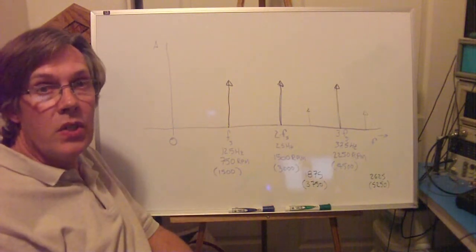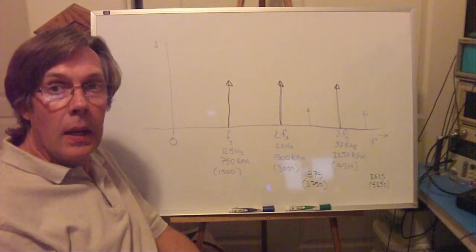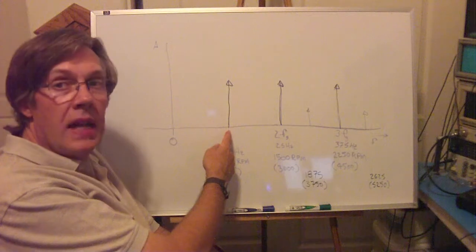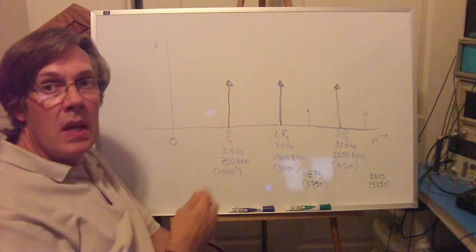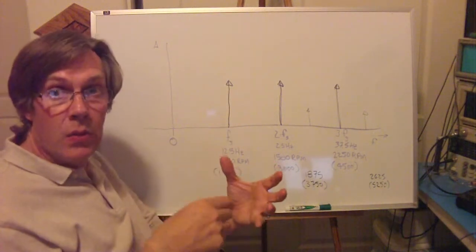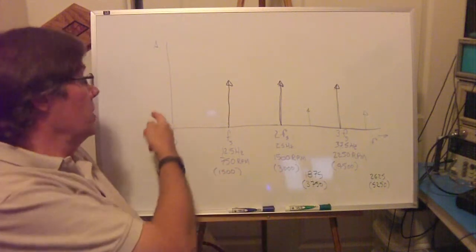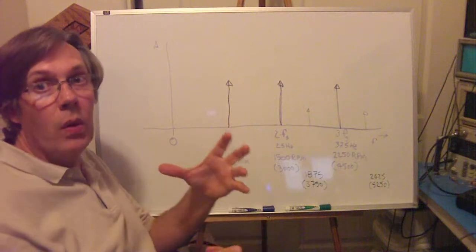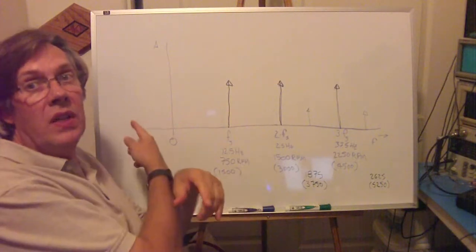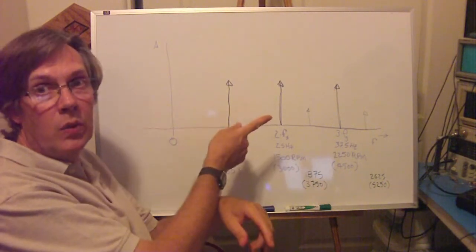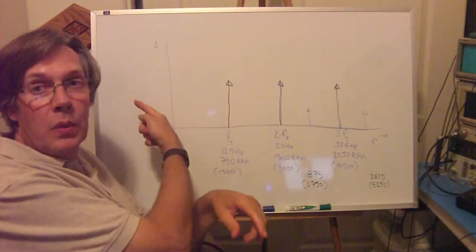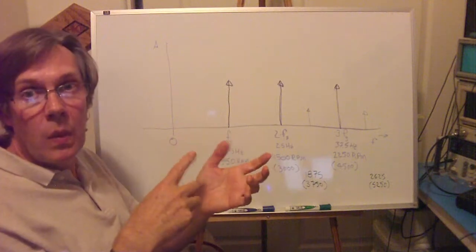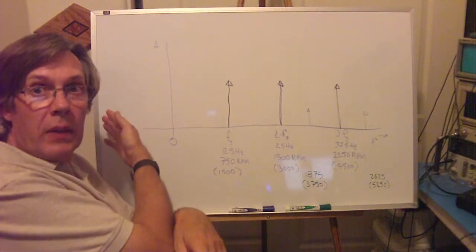And we just saw that in the demo that we just witnessed, where when we're matching the rotation rate with the sampling frequency, if we're a little bit lower than that, it looks like the blade's rotating backwards slowly. And so this region over here is actually useful because we have a rotating system. It has a forward rotation and a backward rotation. So there is such a thing as negative rotation. Rotating forwards we're going to call positive. Rotating backwards we're going to call negative. And we've seen it rotating backwards a little bit. We could spin it backwards if we wanted and sample it, and so that's useful spectrum down in that direction.